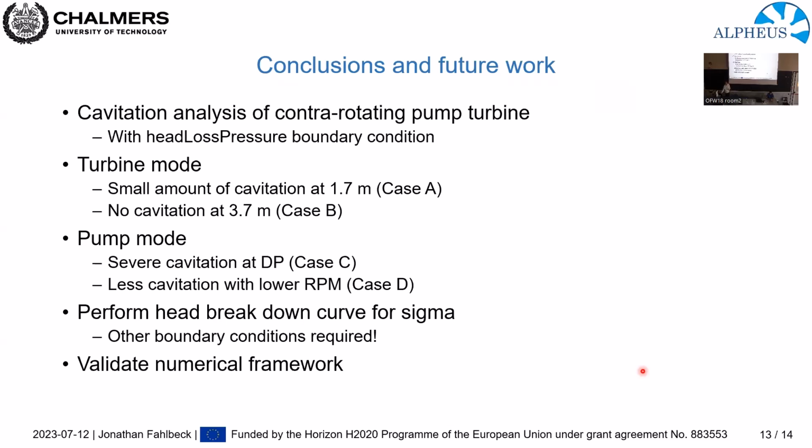So hopefully that operating point can be tested in the lab facility in the future. Another thing that I want to do in the future is to perform a full head breakdown curve, where you basically just change the static pressure on the low pressure side until you see a large drop in efficiency. But that will require that I run the simulation in a totally different way than I set it up now.